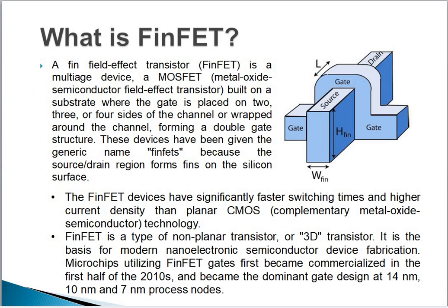Let's start. What is FinFET? A FinFET is a multi-gate device, a MOSFET semiconductor device built on a substrate where the gate is placed on 2, 3 or 4 sides of the channel or wrapped around the channel, forming a double gate structure. These devices have been given the generic name FinFET because the source drain region forms fins on the silicon surface. This is the structure of the FinFET, this is the length of fin, and this is the width of fin, from this point to this point.